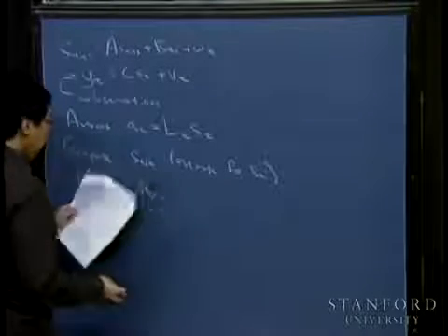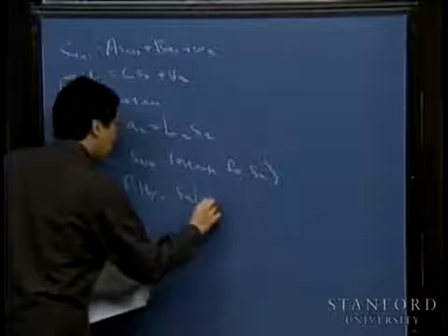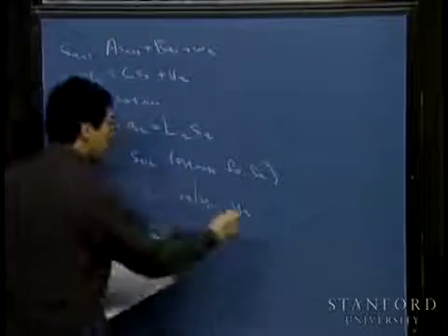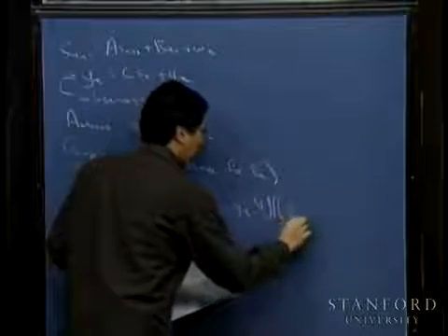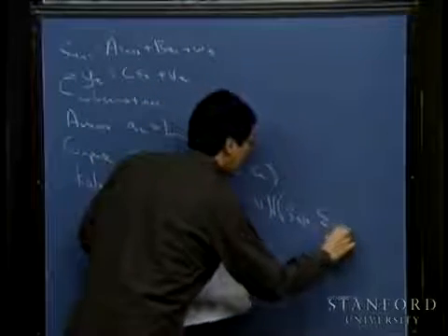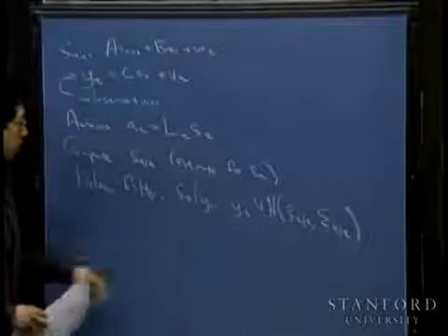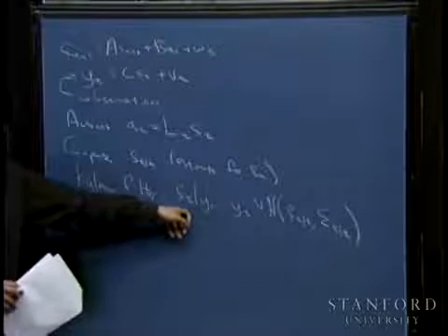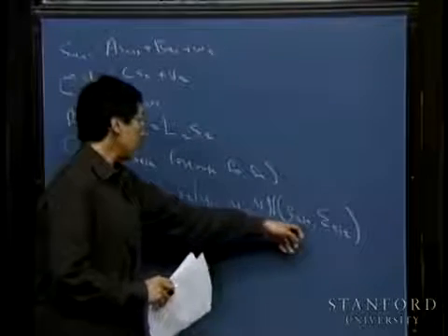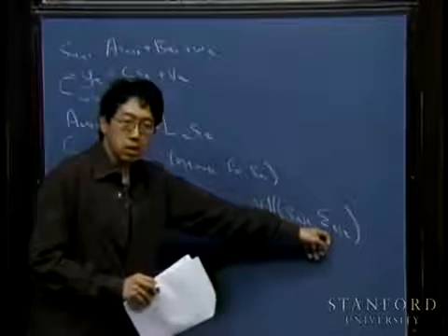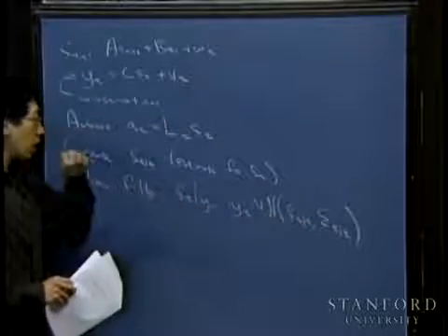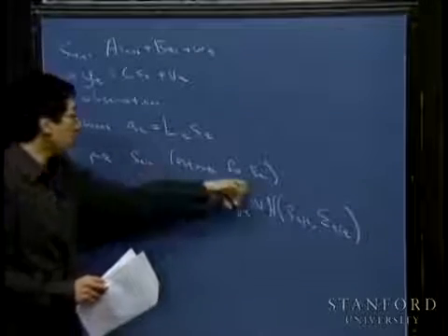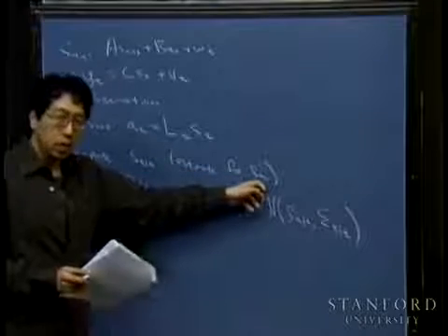We worked out that our posterior distribution of what the state is given all the observations up to a certain time was this. From last time, given the observations y_1 through y_t, our posterior distribution of the current state s_t was Gaussian with mean s_{t|t} and covariance sigma_{t|t}. We use a Kalman filter to compute this s_{t|t}, which is going to be our best guess for what the state is currently.